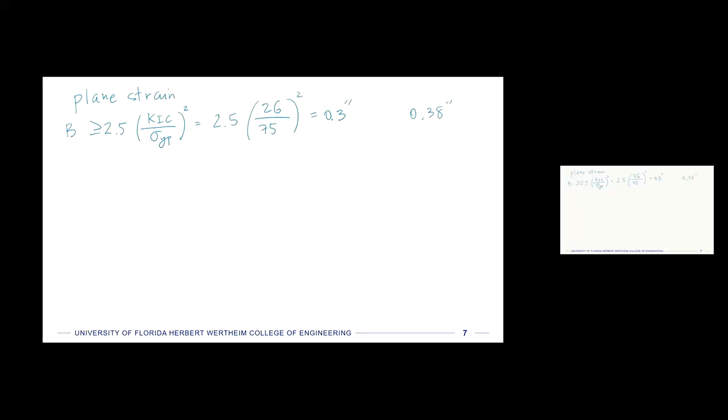Okay, so the equation that we are going to apply, our failure criterion for brittle fracture, is that K1C will be exceeded for failure, so we need to stay below it. Let's write this as an inequality. The example problem doesn't write it as an inequality, but they should.